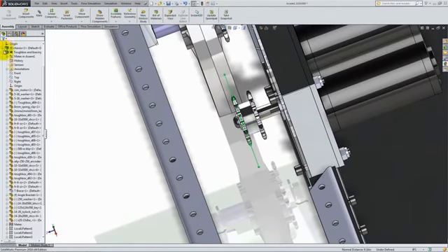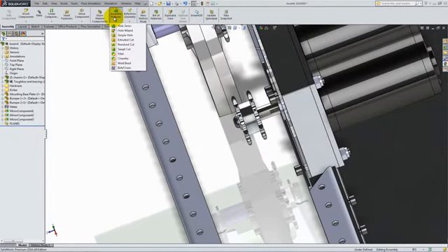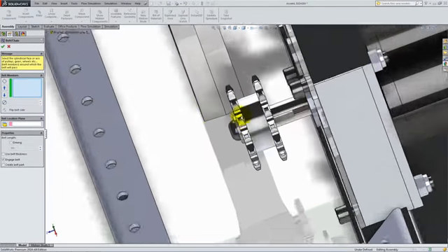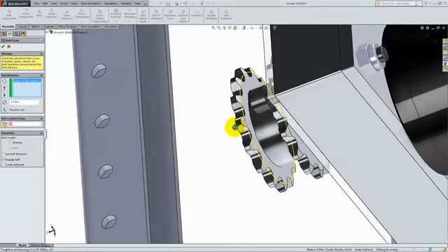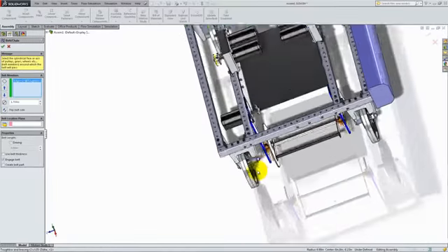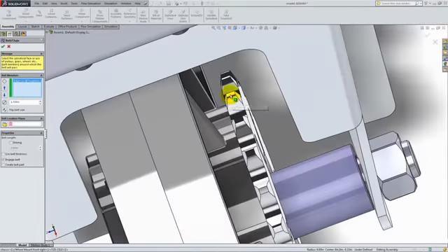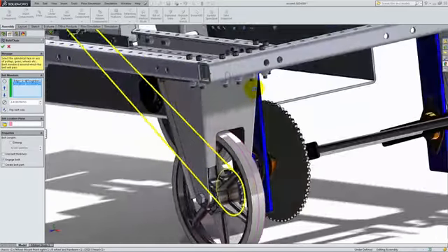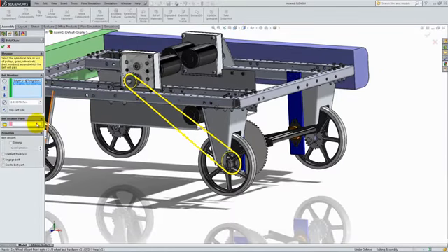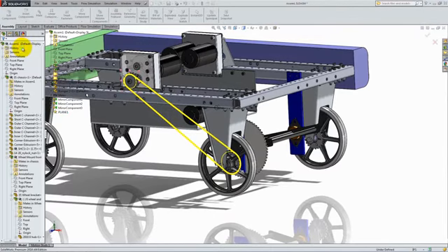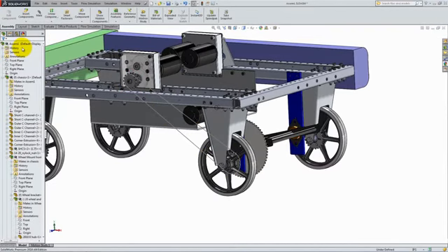To add the belt between the wheel and the motor, you can use an assembly feature called Belt Chain. Select the line that defines the circle on the motor's gear and a face on the wheel's gear. Select the plane we created for the belt location plane and make sure Engage Belt is not checked. Then check Create Belt Part and click OK. At this moment, you can leave the belt as it is, but for visual purposes, we will actually create the physical part.